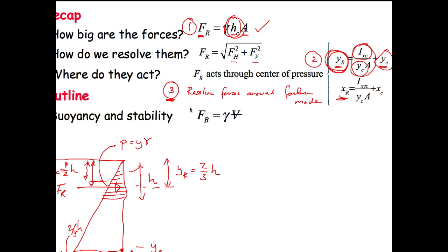And so out-of-balance forces on structures are also applied by buoyancy, and the magnitude of the buoyant force is just equal to the unit weight of the fluid which is displaced, multiplied by its volume, Archimedes' principle, and it acts through the centroid of the displaced mass.